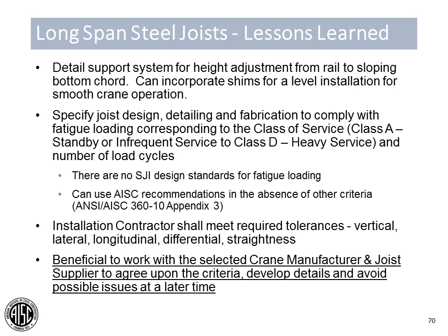Make sure your installation contractor knows that they need to meet the CMAA tolerances in all directions. Make sure that that CMAA figure is included on your design documents and construction documents. And it's always good to work with your selected crane manufacturer and the joist supplier to make sure everyone is on the same page with regard to your design criteria and the developed details.